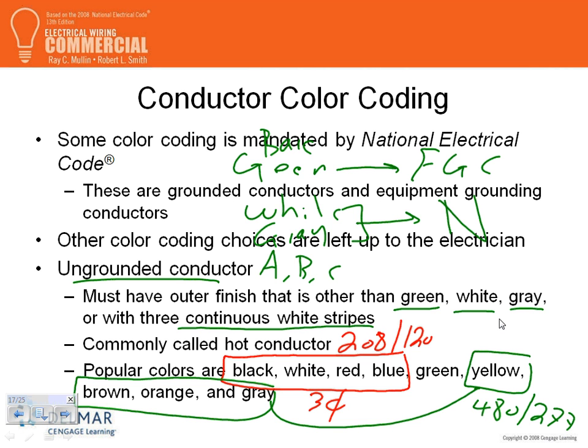Yes, sir. You said for the 208/120 you have black, blue, red, white, and also green. The green is the ground. The green goes with everything. I left the green here because the green goes with this system and goes with this system. The green is always ground. Yes, if you're using cables, you need five conductors for a three-phase system. But if you're using conduit, then you need to pull four wires because the conduit itself will be your grounding. Any questions about this? Very important.